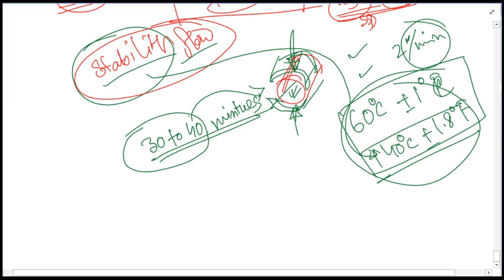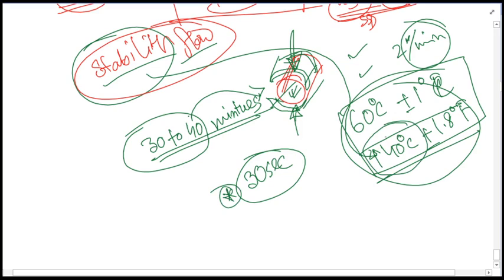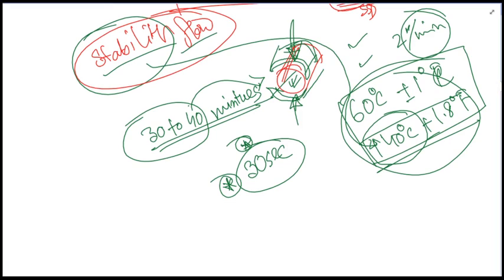When after 30 to 40 minutes you remove the sample from the water, adjust the specimen and start applying load, this time should not be greater than 30 seconds. This is very sensitive again, because you have to maintain the temperature of 140 degrees Fahrenheit, as you cannot apply the load in the water. So after removal from the water and adjusting the specimen, the time before applying load should not be greater than 30 seconds. Exceeding that is prohibited. You must maintain these things as well. That is another thing we have learned here.